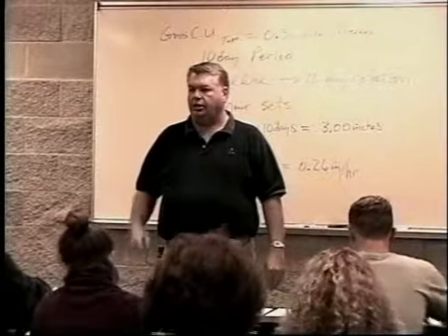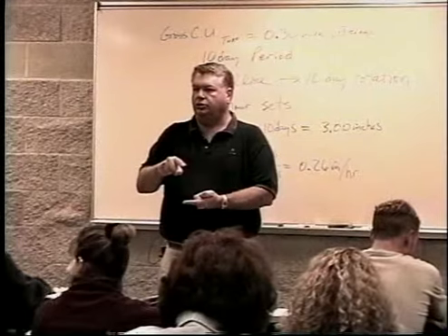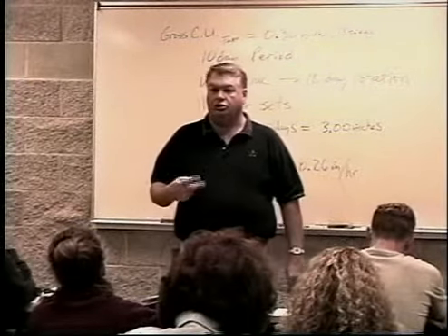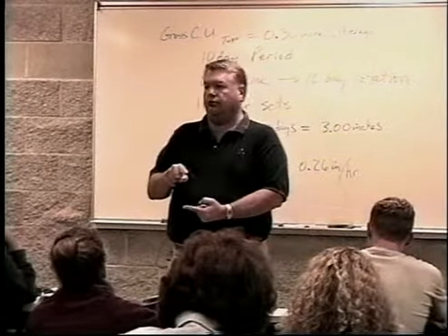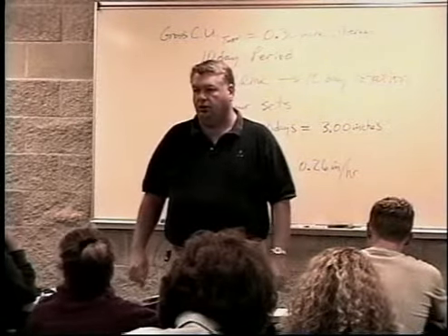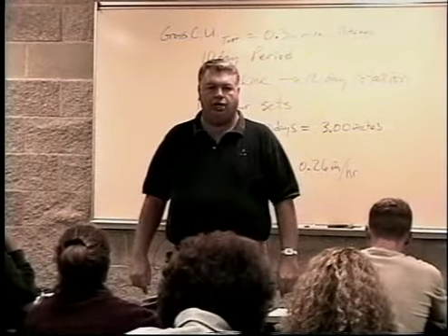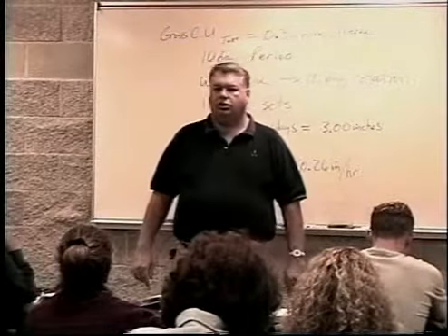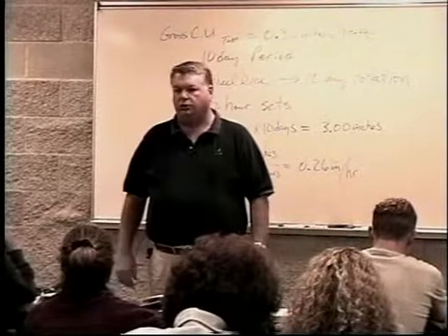Now you can't do that on turf because you're working off of a 6-inch profile instead of a 5-foot profile. Now all of a sudden you got about 2 days in this valley. That 6 inches, you're going to lose its effective value in 2 days in this valley. So if you schedule more than 2 days between irrigations in July and mid-August, in this country, in this particular valley, you're going to have stress on turf.